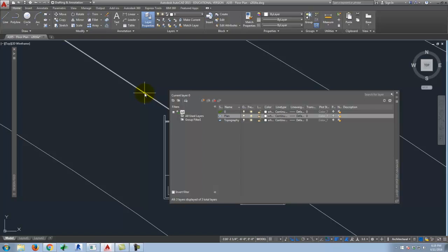All the other colors remain exactly the same. So if you turned a line red, it's going to be red when you print it. If you turn a line dark gray, it's going to be dark gray when you print it. So a dark gray line here on a black background might not show up as well as it's going to show up on a white backdrop. So it's a little bit confusing, but it's, again, to help our eye strain because we're going to sit at the computer and draw for so long.